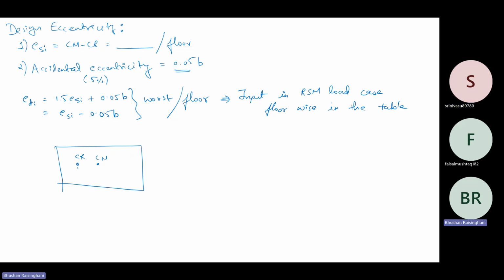Okay. So this is a base shear here which is acting on the CR. Basically, it should be acting at this particular point here. So we have to transfer the force V to CR. It will get transferred here, but along with that, there is an EDI. So this force will generate a moment equal to V into EDI. This is the way the force will get transferred from CR to CM.